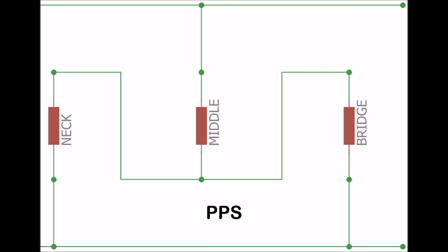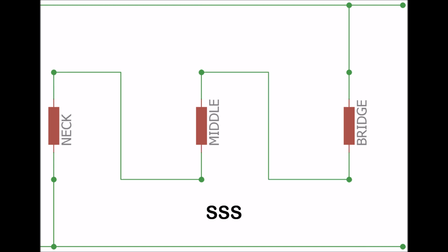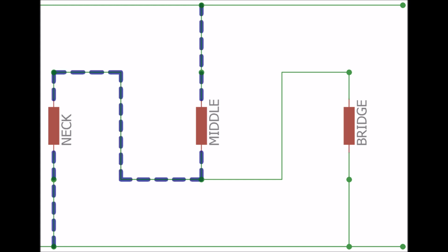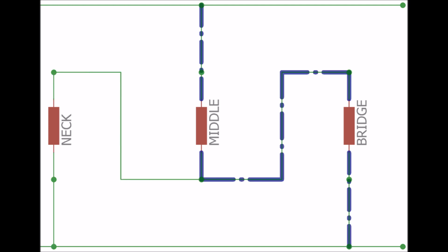After the series connections are defined, the compound connections for 3 pickup combinations, PPS and SSP, are determined from the paths defining the SS and SSS combinations, using switch logic operations. The definitive combinations are the SSS and PPS combinations, and they essentially make up the entire switch system operation. The PPS combination is built around 2 SS combinations, each terminating with a common pickup.